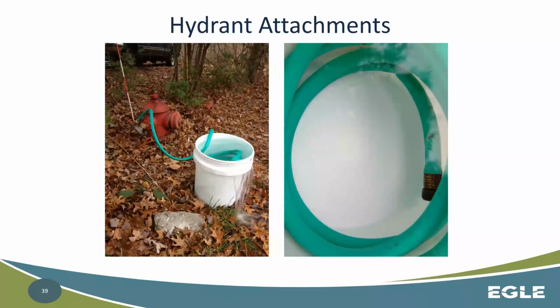Other attachments, a lot of times folks want to try to use hydrants as temporary water for construction or other activities. So you can easily find connection to this. In this specific instance, what was happening here was the municipality was trying to flow a hydrant into this bucket to find out if they were having discolored water come in. So that's why a very nice white bucket with the hose dribbled into it to just flow it and see what's going on.